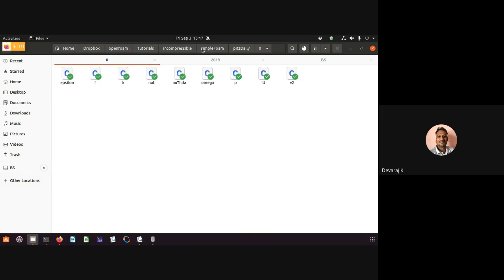That means if you go to constant, I've seen a couple of folders where you will have a separate file called turbulenceProperties. turbulenceProperties itself is a file where all your k, omega and all will be defined, and you will be using that also. So that option is also there, or you can just go to the 0 folder and check for it. If you check your p file, already I've shown you the p file, it will contain your dimensions, what type of gradient, boundary conditions, or physical field, all those things.